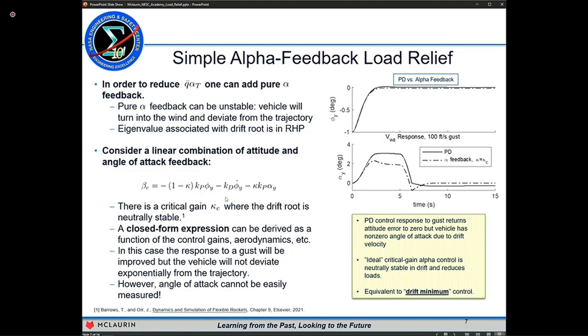Now, because we're doing attitude feedback either way, this ensures, regardless, that the rotational dynamics are stabilized. So you get approximately the same aerodynamic gain margin for the vehicle, whether you use kappa equal 1 or kappa equal 0. What this is controlling is what happens to the translation dynamics.